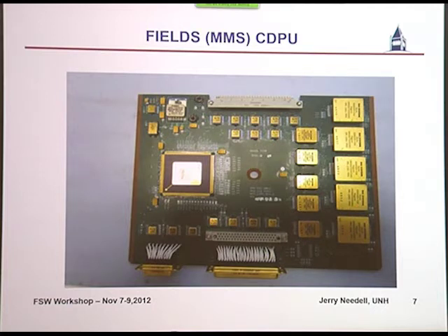They're left off, so we can test the board rather than putting on these expensive and difficult to work with parts. They can make sure that there aren't any other problems to avoid rework. If there's a problem with the board, it's a lot easier to stop at this point than it is to put these parts on it and then take them off. It also allows us to exercise the system really early in the development.